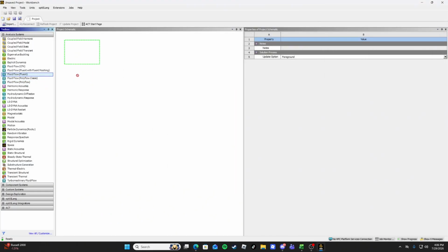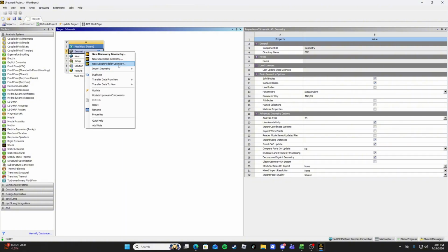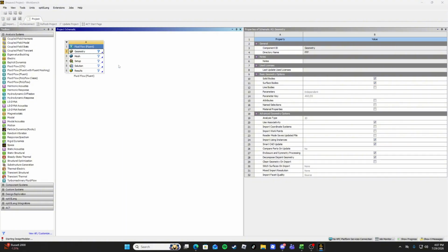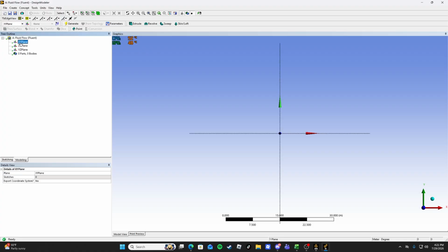Okay, so first things first is to open Fluid Flow Fluent and make sure our geometry is in 2D. Then open this in the design modeler. Okay, now that we're here, select to see the YX axis and go on the plane. First, gonna make sure we're in inches, because that's the requirement for the specifications.